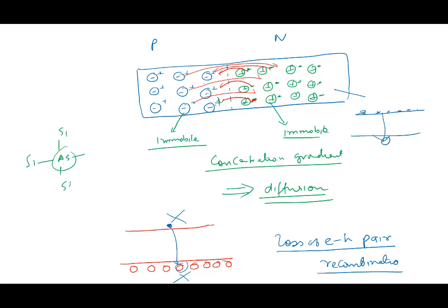They're lost. So invariably what is happening is this region that you see here is starting to get charged, because this was neutral. There was an acceptor ion and there was a hole, but that hole is now gone. So it begins to get charged. Increasingly, your PN junction begins to look like this.